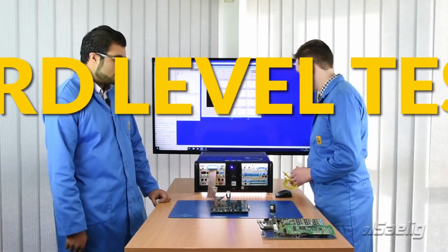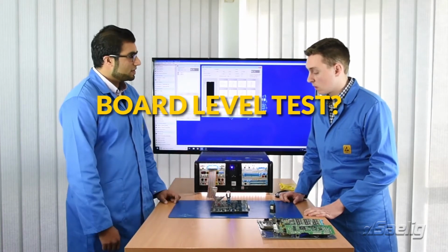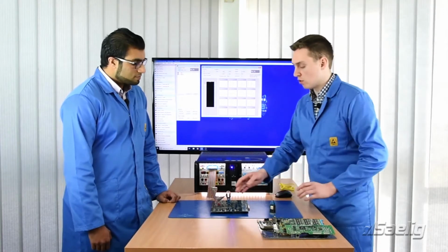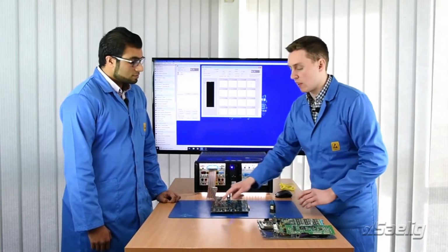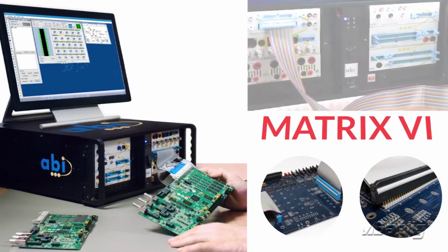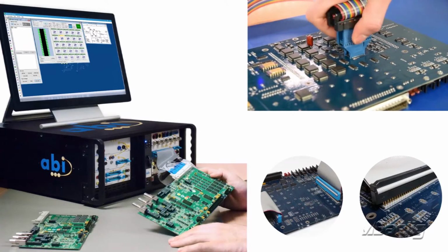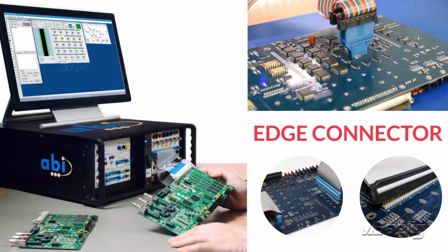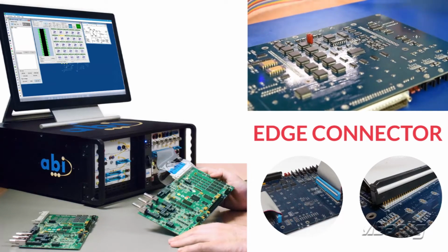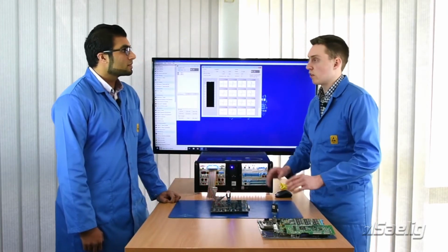I see, very interesting. So we've been talking about component level tests so far. What about a board level test? Can we do that? Of course you can. You could use the edge connector. You could choose a reference on your board, so it can go from every one of those pins to that reference, and then you can compare that against another board. With matrix VI, you can use the edge connector and do the reference like we did with this clip inside the IC, and instead of using an area on the board, like a ground or another component, we can use another pin. So it goes around that circuit, back to the other pin, across all the pins on your edge connector.